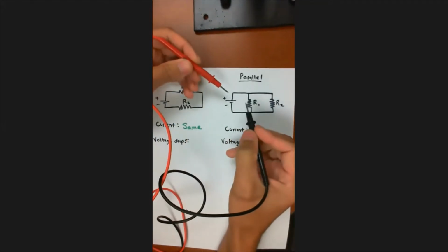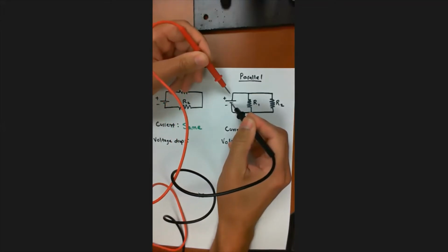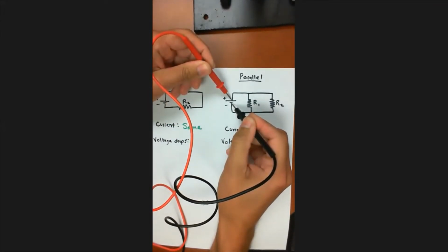If I put the leads of my probe, one right here on the negative side, and one right here on the positive side of the battery, and if it's a 12-volt battery, what am I going to read on my multimeter? Hopefully, I read 12 volts, or pretty close to it, right? If you've worked a lot with 12-volt batteries, you probably know that when they're fully charged, they're not actually 12 volts.